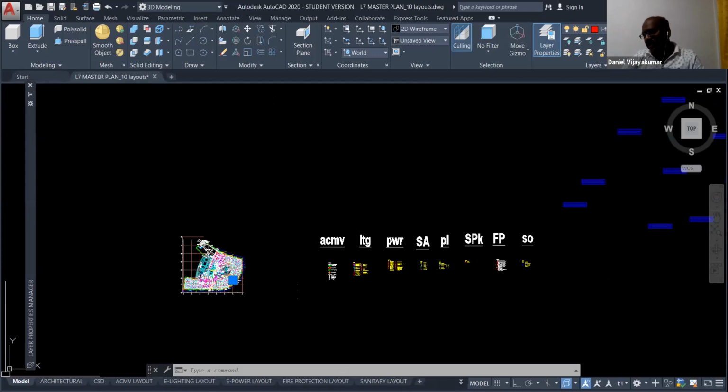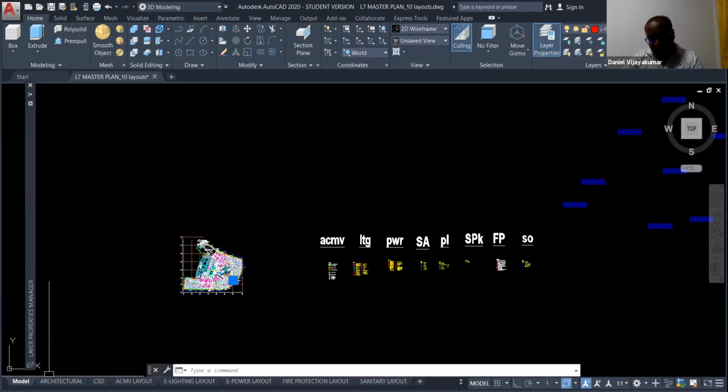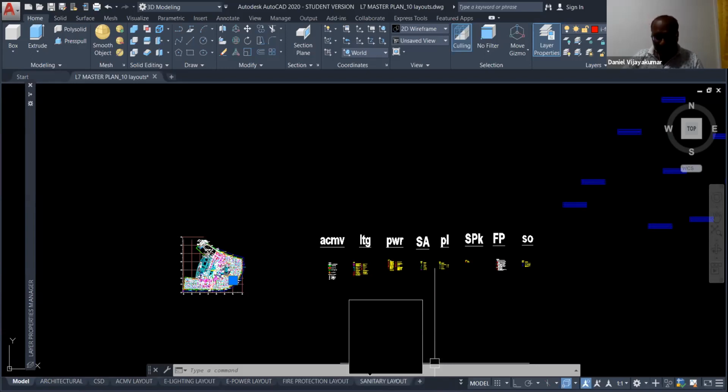In your drawing, after the model space, there is one more icon, like Excel sheet 1, sheet 2, 3, right? The same way here also. Some people have it, some people don't. If you don't have, there might be a plus symbol. When you bring your cursor there and click, automatically it will show you new layout. You can click that if you don't have. If you have, you can use that existing layout. Also, the existing layout is the other drawing. So in that case, you have to create the new one.